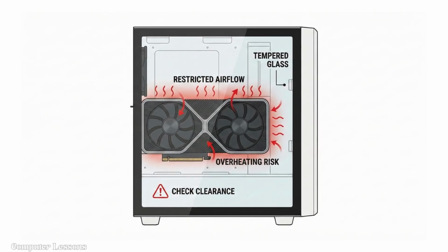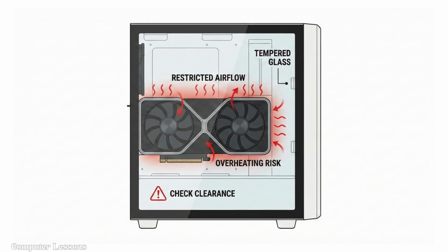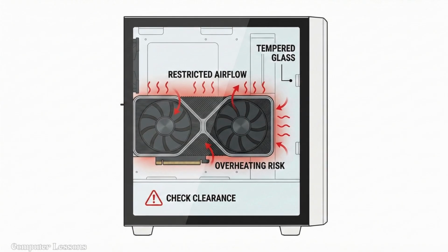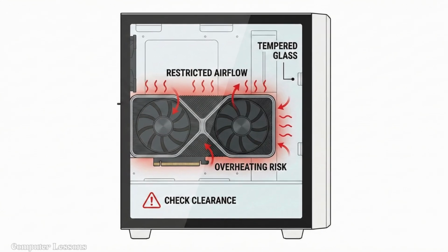If they are pressed against the glass, they cannot pull air in, and your beautiful aesthetics will result in a loud, overheating system. Always check the clearance before choosing a vertical mount.